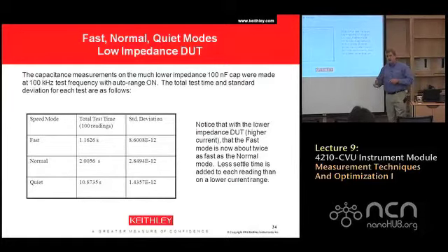So if you were to do any transient testing, like a test that we used to do in the old days, deep level trapped spectroscopy, where we would pulse the device into a state and then watch the capacitance recover. In many cases at room temperature, we needed to see recoveries in hundreds of microseconds. This instrument won't do that. But a lot of times at Kelvin, at cryogenic temperatures, you can easily see the device recoveries at 5 millisecond acquisitions.